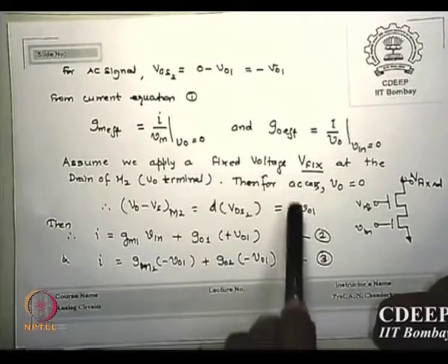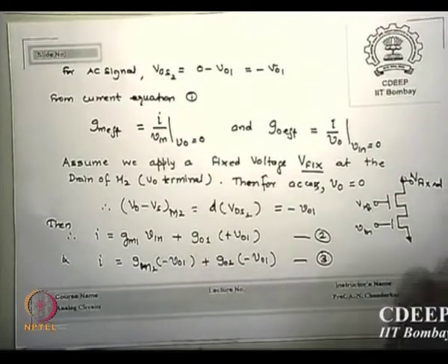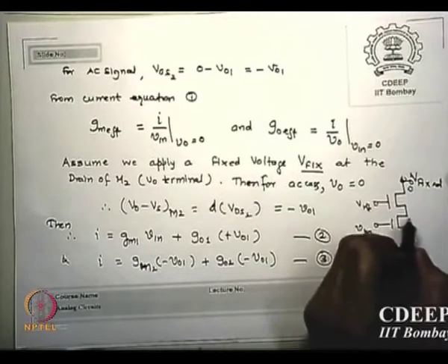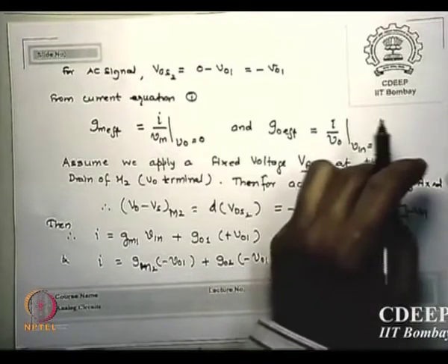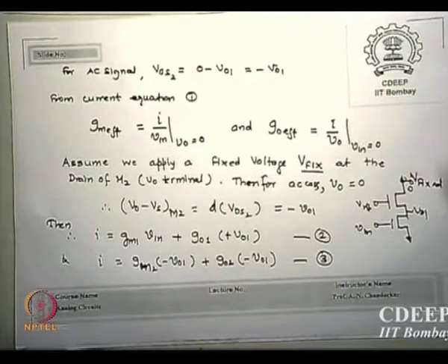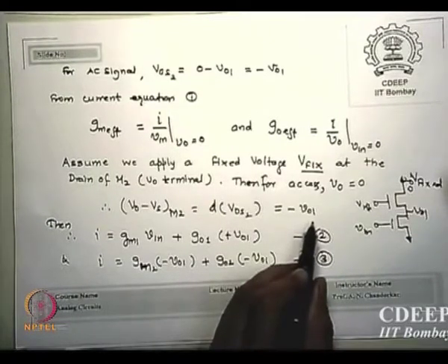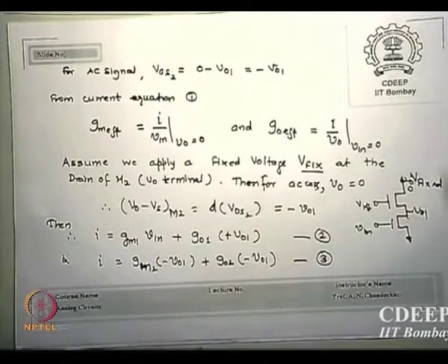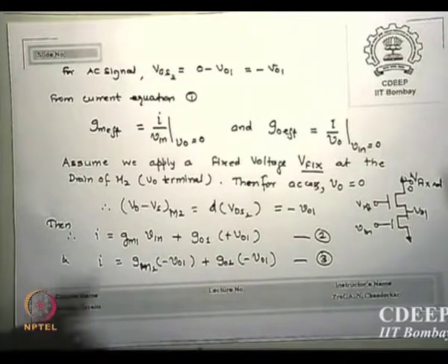So I made that condition true, and then I write VO minus Vs, which is nothing but the variation of VDS2, is nothing but 0 minus, please remember this is 0, this is VO1. So how much is the change in VO1? AC value 0 minus VO1, which is minus VO1. So small VDS, that is AC, is minus VO1.